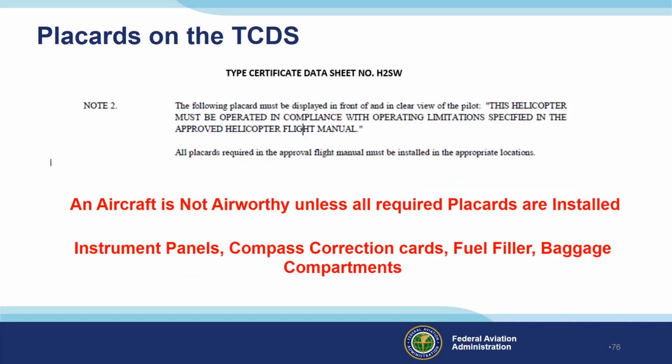Now, the type certificate data sheet is also going to state something about placards. Here's a statement from, I believe, that Bell helicopter type certificate data sheet. Talks about a placard that must be displayed in clear view and in front of the pilot. And it also says all placards required in the approved flight manual must be installed. So an aircraft is not airworthy unless all required placards are installed.